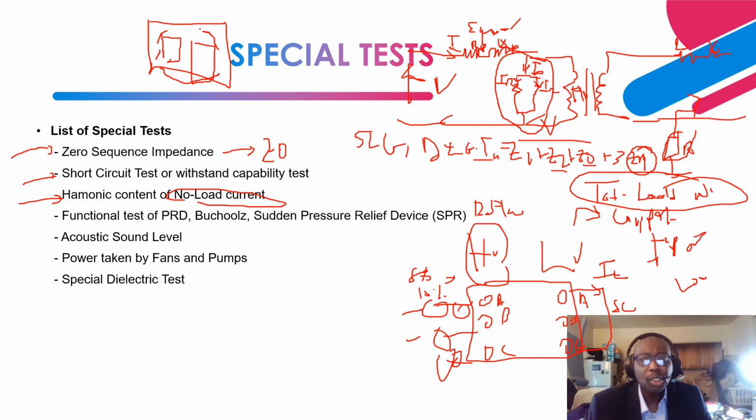During energization of the transformer, with the secondary side not connected to a load, the differential relay will see this as a fault condition, because primary current is flowing here, and the secondary current is zero because there's no load connected.